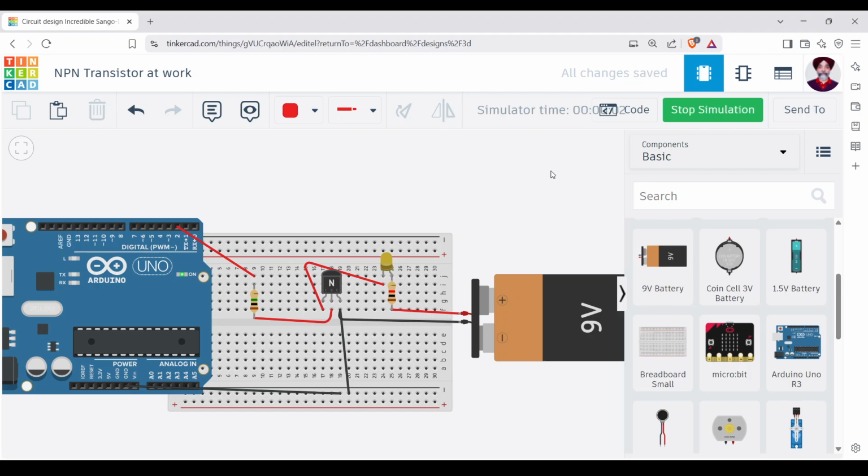Alright. Let's see now what happens. Initializing, on, off, perfectly. It is working perfectly fine. So now I'm not using a physical switch. I'm using Arduino to do the same task. Now, if Arduino is basically controlling this particular resistance as on and off, please remember the voltage to the LED is not being supplied by the Arduino.